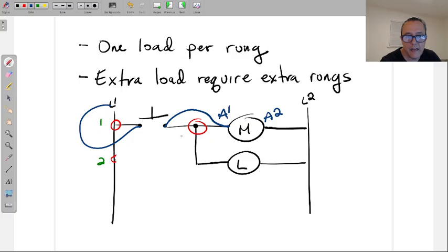All right, this wire cannot, again, we're not going to cut the wire going from the push button to the motor starter, cut it right in the middle like we do with a regular electrical circuit and splice it with some wire nuts. We do not splice in motor control. The reason being is we need to test the wires, we need to measure the wires to see if there's voltage flowing through for troubleshooting circumstances, and undoing a wire nut can cause chaos.